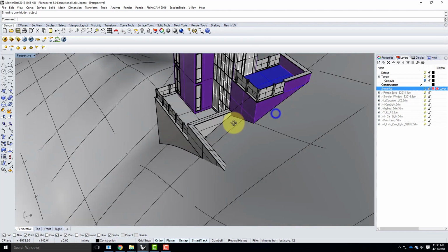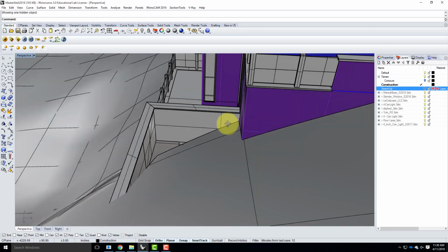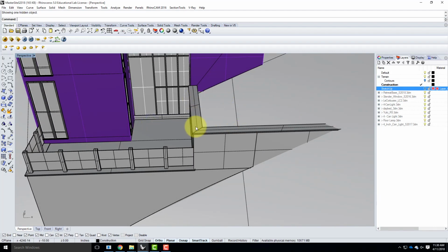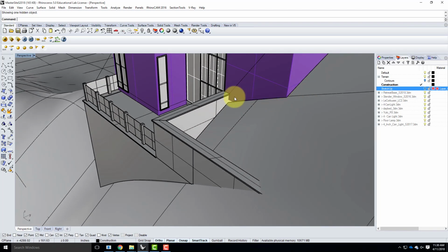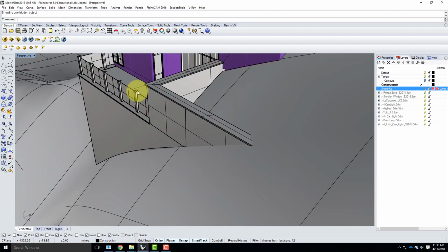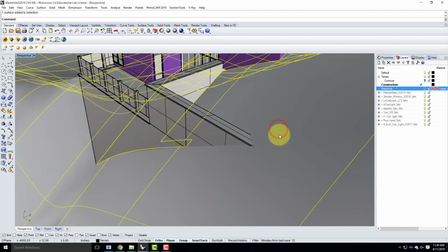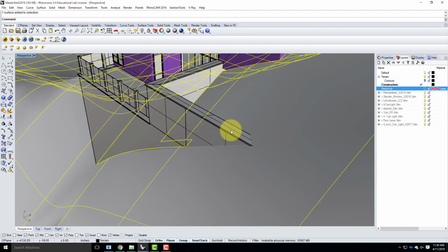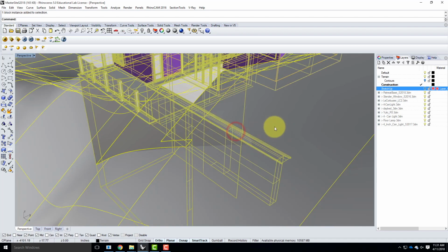I have another issue, though, and that is that this back edge doesn't quite correspond to the way I wanted it to go. I wanted to have a little bit of a retaining wall here. So I need to deal with fabricating a bit of a surface right there. I can tell where this wall intersects the surface by where this and this intersect. So let me use an intersect command.